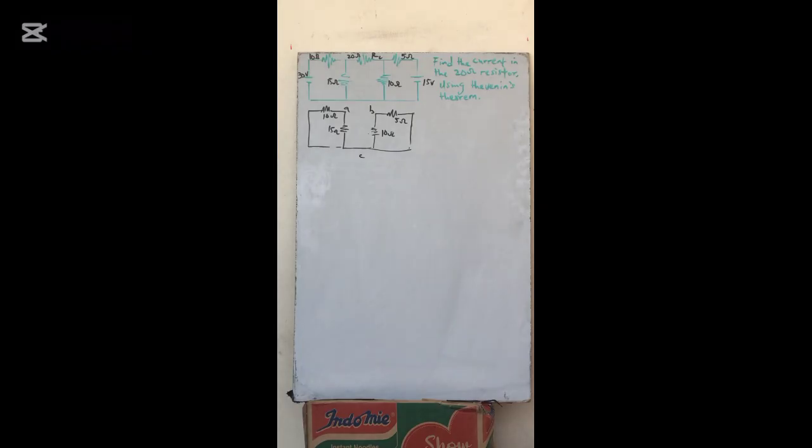So now, when we did it the other time, we also calculated the Thevenin resistance. Now also we are calculating the Thevenin resistance, and it's very, very simple if you are going to flow with it. Look at this now. This is in series with this. This is also in series with this. But when they join together, they will not become parallel to each other. So that means that 10 plus 15 is in parallel to 10 plus 5, right? So we are going to be having 10 plus 15, they are in series, in parallel with, open bracket, 10 plus 5.